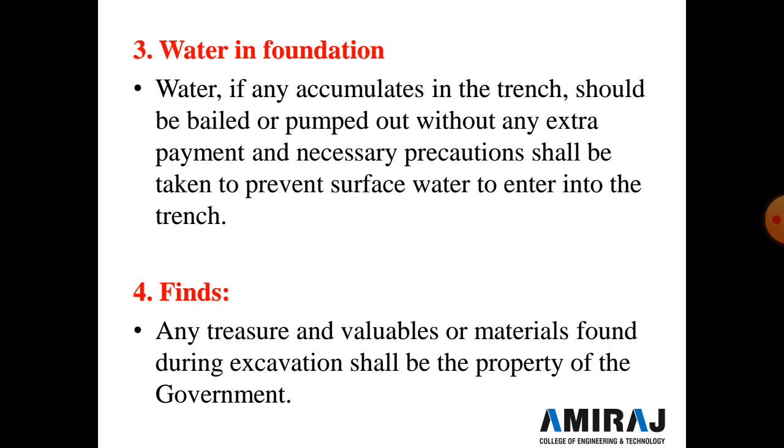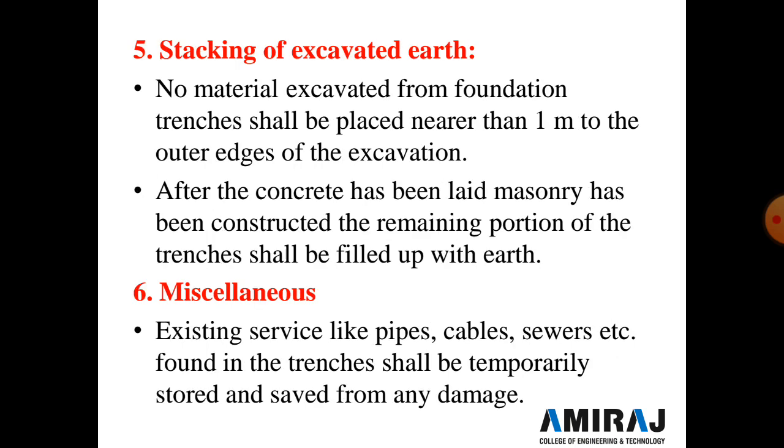Now the fourth point is finds. Any treasure or valuable material found during the excavation shall be the property of the government. And the fifth one is stacking of excavated earth. Normally no material excavated from the foundation trench shall be placed nearer than 1 meter of the excavated area.